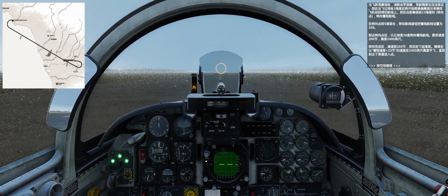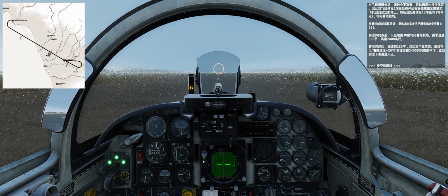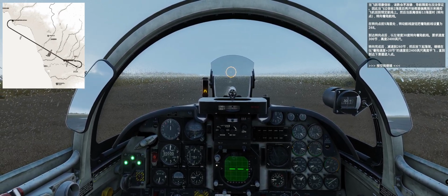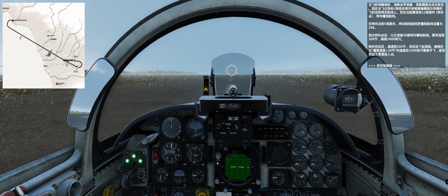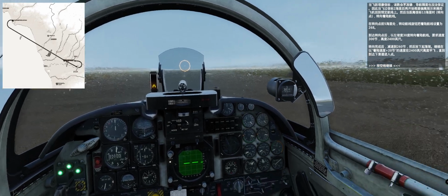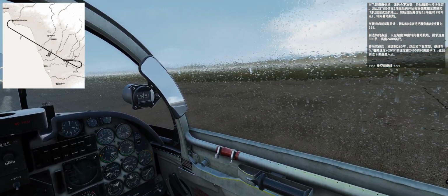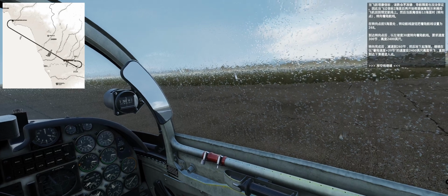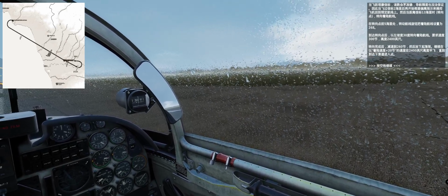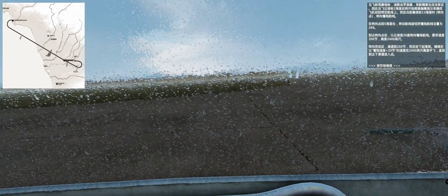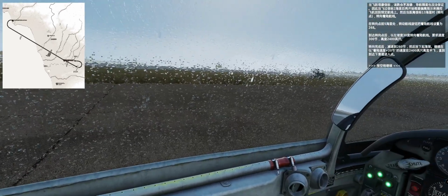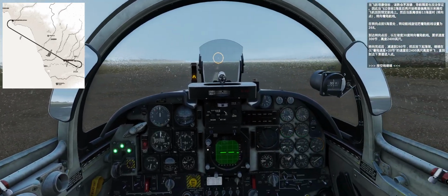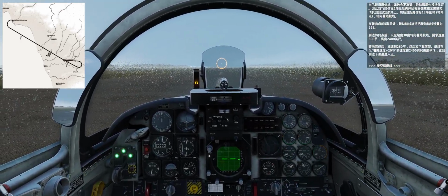When this point is reached, turn towards the landing course with 30 degrees left bank, a speed of 300 knots while maintaining an altitude of 2,400 feet. When the turn is performed, reduce RPM to reach 260 knots and then extend the landing gear. Continue level flight at an altitude of 2,400 feet and a landing speed of plus 20 knots up to the glide path entry point. Press space to continue.